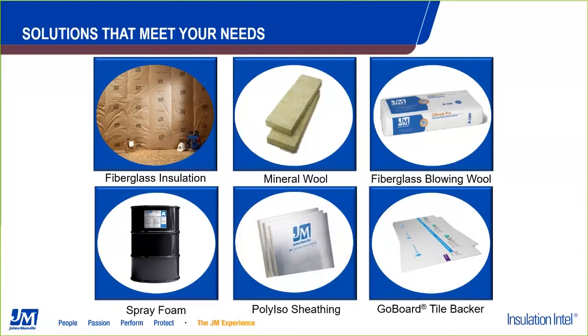So anything you can dream up in terms of a cavity space, we can fill with this type of insulation. Mineral wool products have greater acoustic characteristics, definitely even better fire resistance than fiberglass, and come in various types of applications, including some that are silicone treated for exterior cladding systems. You can put those on your exterior wall without any worries about an NFPA 285 requirement.